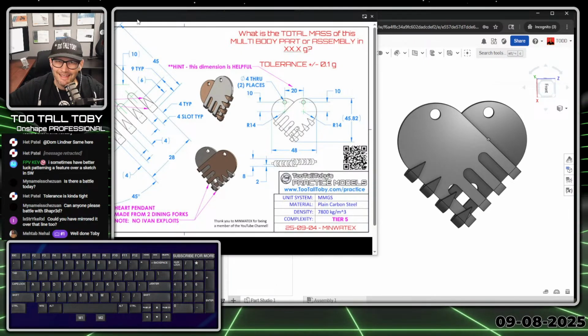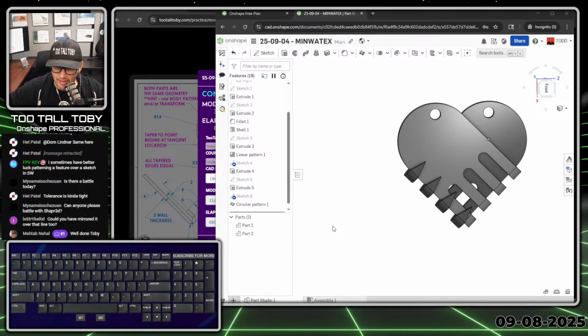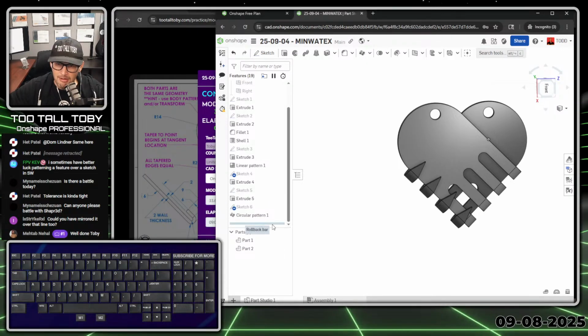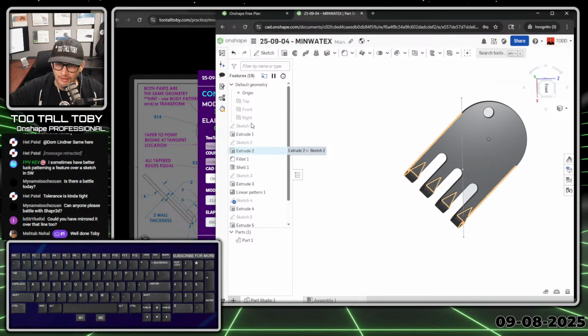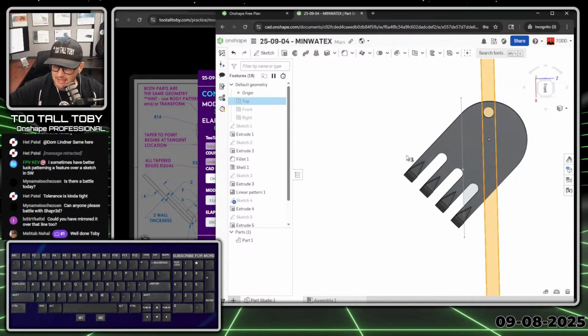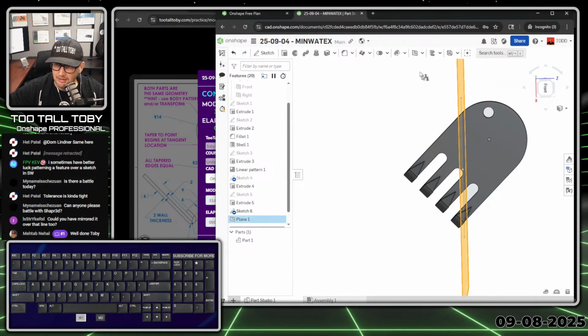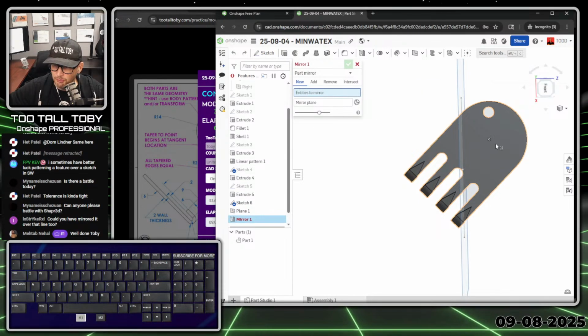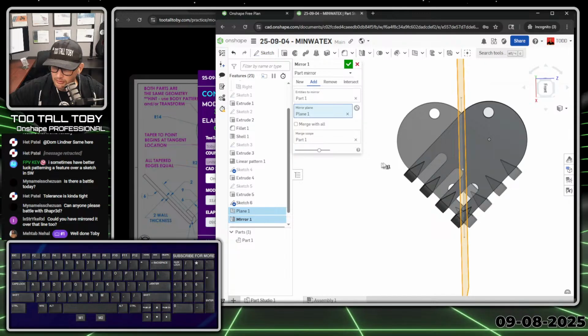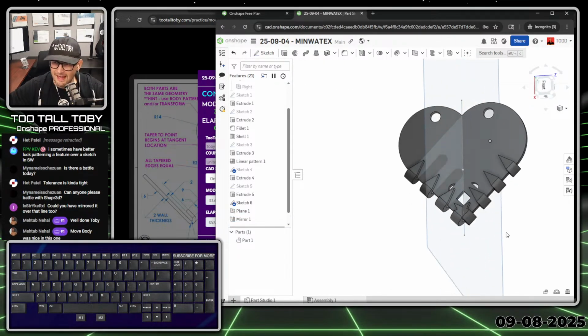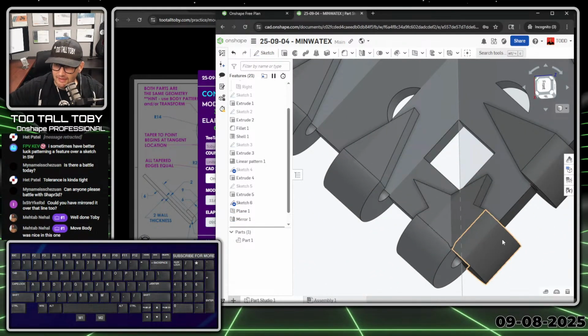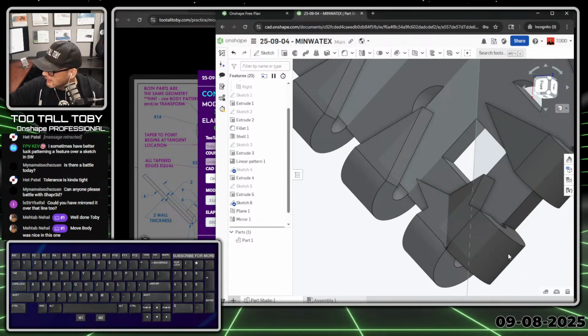It's just a remix. But the question from Striker was, could we just mirror it instead? You could definitely just mirror it to get the correct mass, but I don't think the geometry is going to look right. So if I take the top plane here, and I take this point, and then I do reference geometry plane, and make a new plane there, and then I use that plane to do a mirror, and then I say this is what I'm going to mirror. Whoops, this is the plane I'm going to use. See, I think that's the problem. I think the tines will end up overlapping.